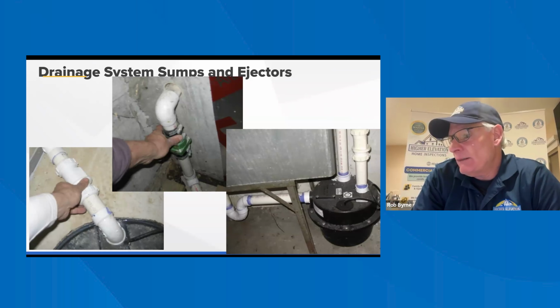All good stuff. Drain, waste, vent basics. So basically, whenever you have water, you always need air behind water for the water to flow properly. So the vent system protects the trap seal on each fixture by preventing pressure imbalances that can cause siphoning or allow sewer gases into the house. Each trap or fixture should have a separate vent connected to the main vent system, with all vent pipes sloped to drain and a minimum size of 1.25 inches.